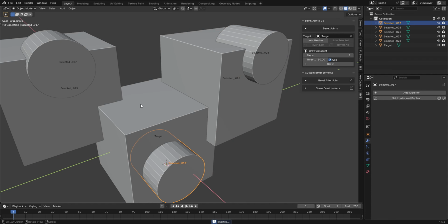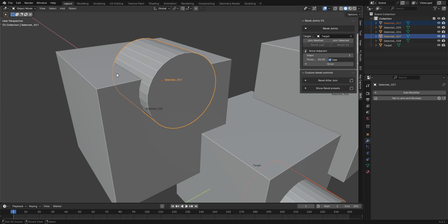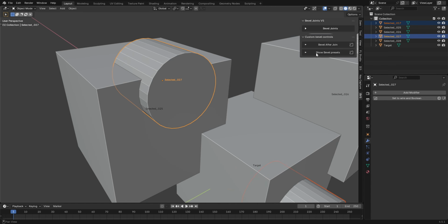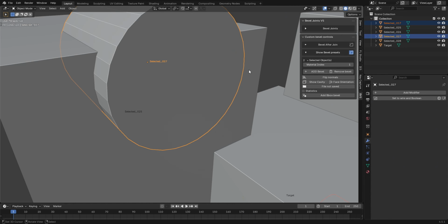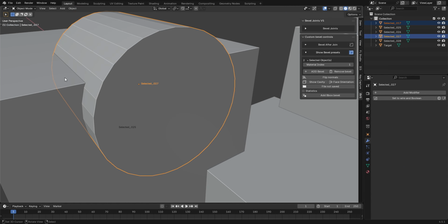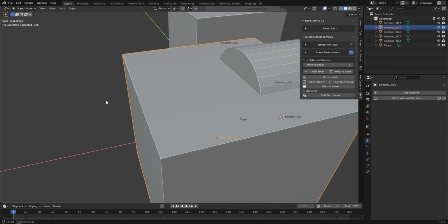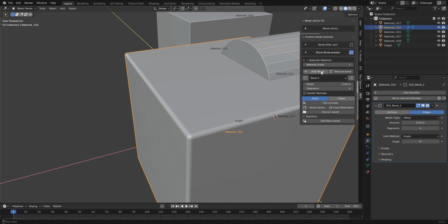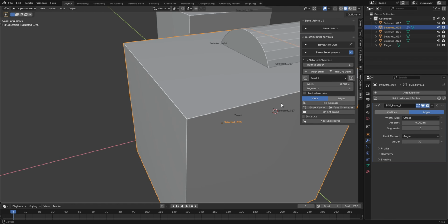And now what we could do is you can individually grab any object that you want, and you can add a bevel in the third area of control, which is a custom bevel area. Now, what I really like about this is if you have a nice hard surface model, you can come in here and add bevel, and you'll have an enum list of different bevel levels. You can then just click the arrows to increase or decrease your bevel size with segments, everything, and of course, always harden normals as you wish.